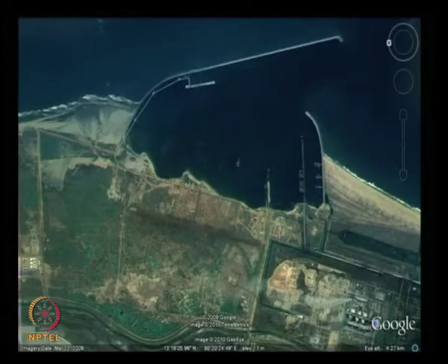In Ennur port we have made a stockpiling of an artificial nourishment using the capital dredge that is shown here. So this is the Ennur breakwater, northern breakwater, southern breakwater, and as they have started construction of this breakwater, the shoreline has advanced maybe about 500 meters, and whatever material they used to create the basin they put it on the stockpile on the northern side. This is a natural deposition, this is artificial nourishment as a stockpile. Now this stockpile is getting eroded, as you see here some portion has got eroded, and then they have to do the maintenance dredging of this.